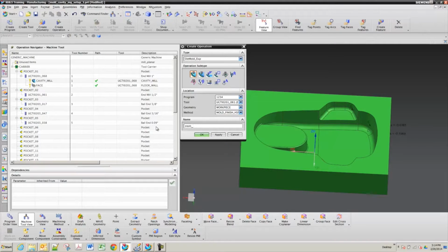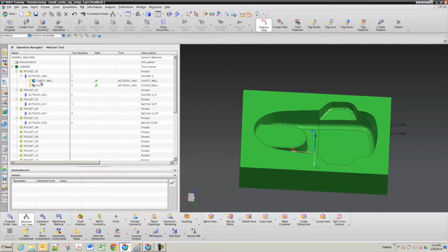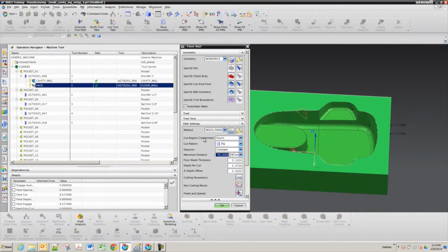If you go back to your tool path of your 1 inch, the face finish. Look at mine. Oh, it's because you did the speeds and feeds thing, right? Yes, that's what I was laughing at. So you could just set the step over back to like 75% or something. Hit OK. Or right there.